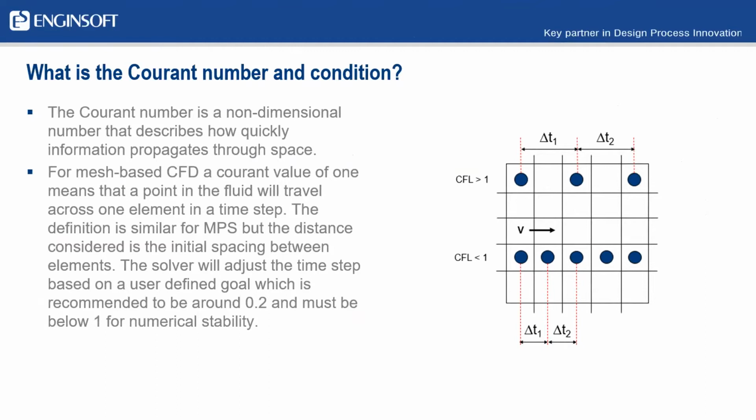Sometimes customers come to me and say, "Chris, my particles are exploding, or they're going beyond wall boundaries, and that's not supposed to be happening." Well, what's happening is we've defined our time step to be too large, and we're allowing particles to travel too quickly through space. So we'll see unrealistic behaviors such as particles passing through walls.